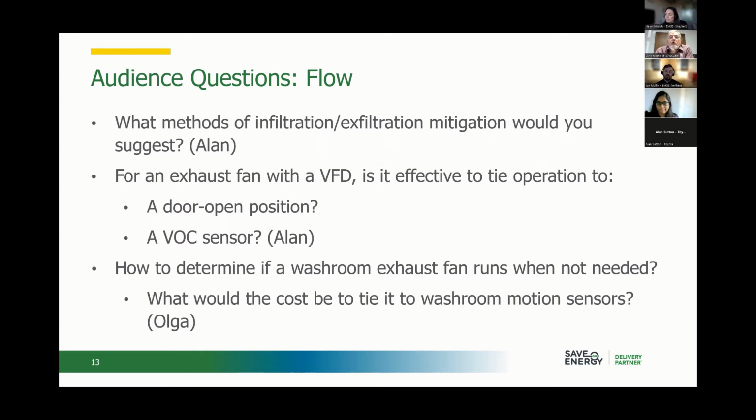But you always want to also be exhausting out of the building, in which case the logical place to exhaust a determined amount of air is out of the washrooms or out of some other area where you've either got high heat generation or other. I mean, in the olden days in office buildings, there was a reason why they used to put the photocopiers all near the washroom. It's because the washroom became that collecting point for exhausting a certain amount of air.